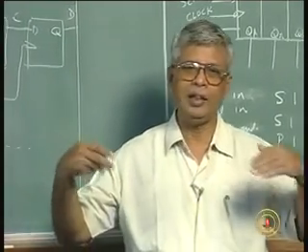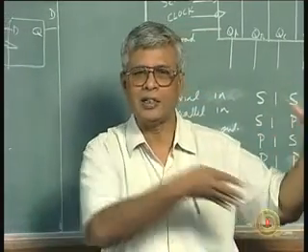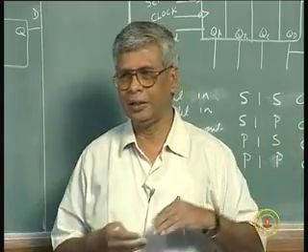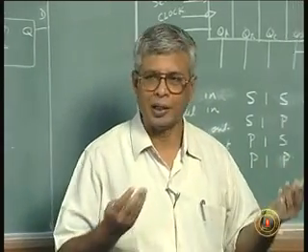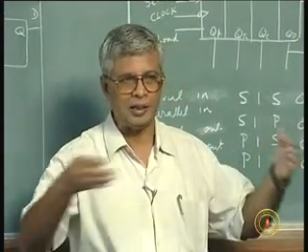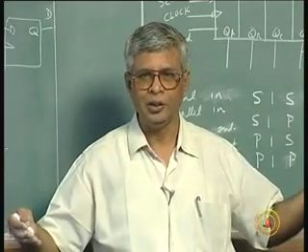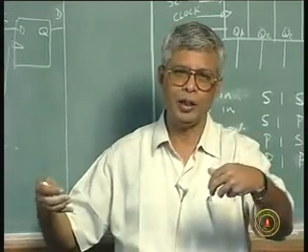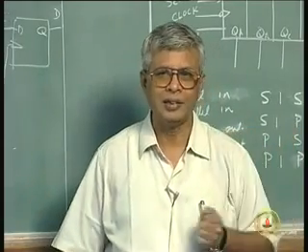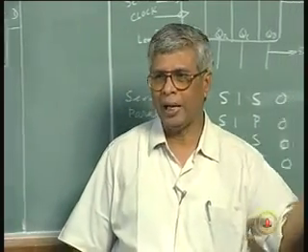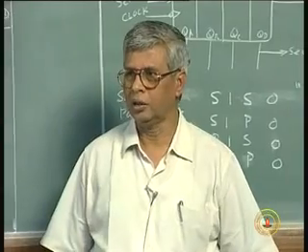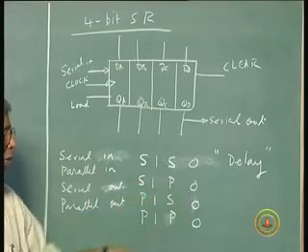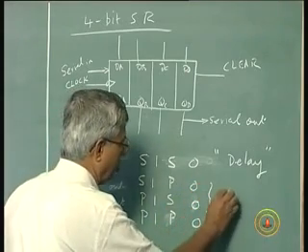Because the limitation is the telephone line, not the generation of data. I want to send a mail to you. My computer can also give you parallel output, and your computer can also process parallel. But in between, the medium is serial, the telephone line. So I have to convert my parallel data into serial mode data and send it to you. That is what my modem does, and your modem gets it back into parallel. Is that right? So these two things are covered: serial input, parallel output, and parallel input, serial output. Examples are modems.